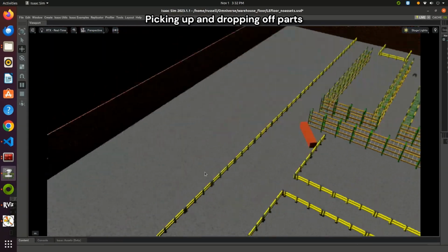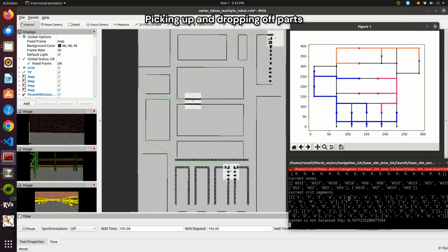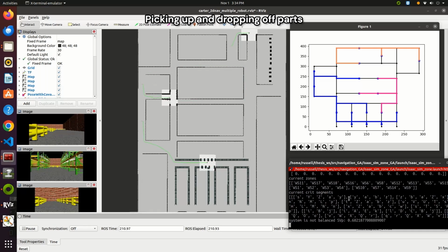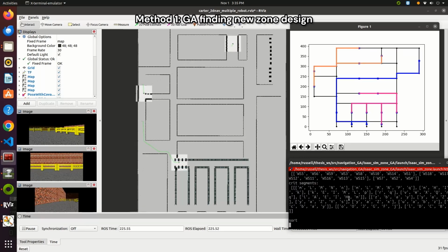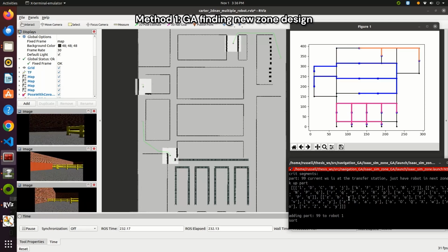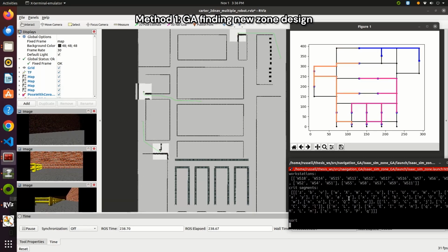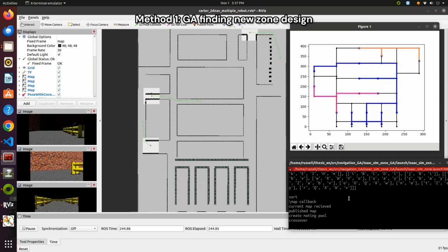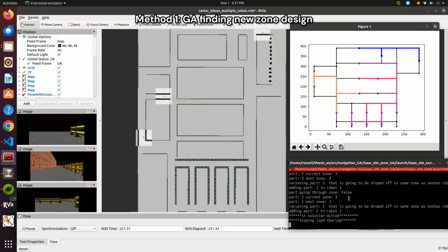This sorting method prioritizes parts based on the shortest completion time, while also taking into consideration how long a part has been in the robot's queue. After some time, and after an imbalance has been detected, the algorithm will go into zone repair. During zone repair, the system will restart genetic algorithm or simulated annealing to find the optimal zone design based on the current recorded data. In this case, the optimal zone design is one that most balances the load of each robot.